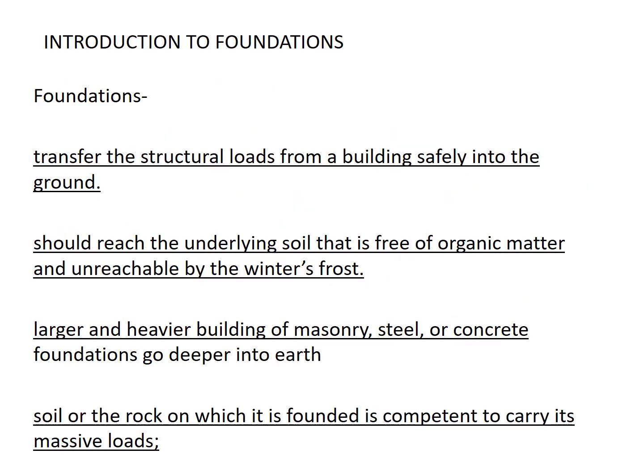So a function of a foundation is to transfer the structural loads from a building safely into the ground. A backyard tool shed may need only wooden skids to spread its load across an area of ground surface, whereas a house would need greater stability, and consequently its foundation should reach the underlying soil that is free of organic matter and unreachable by the winter's frost.